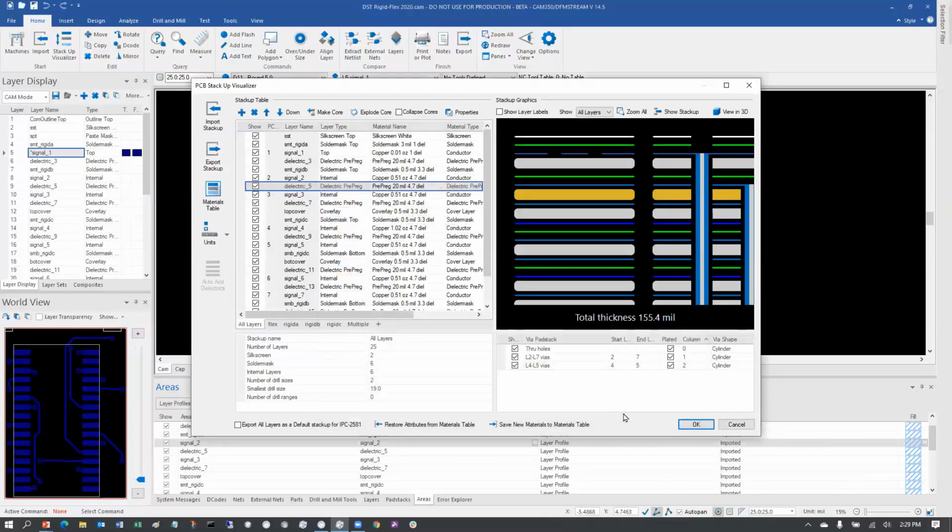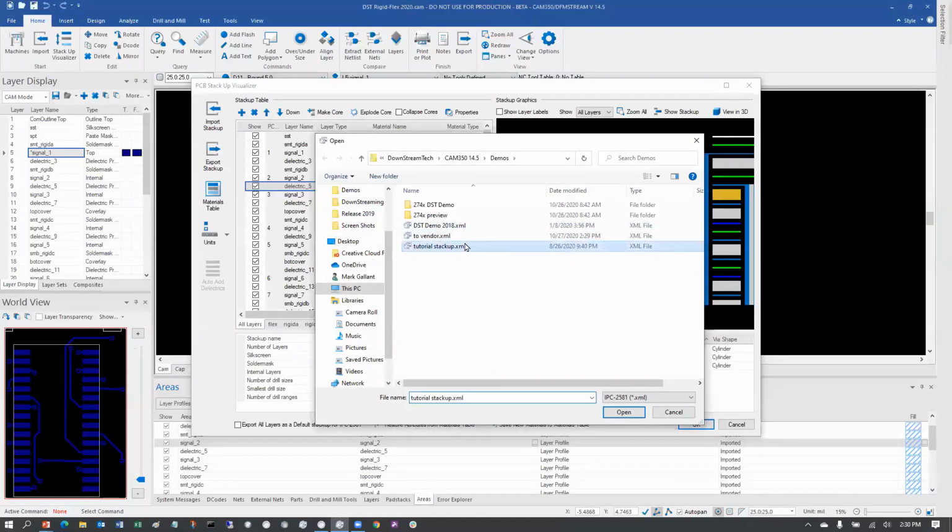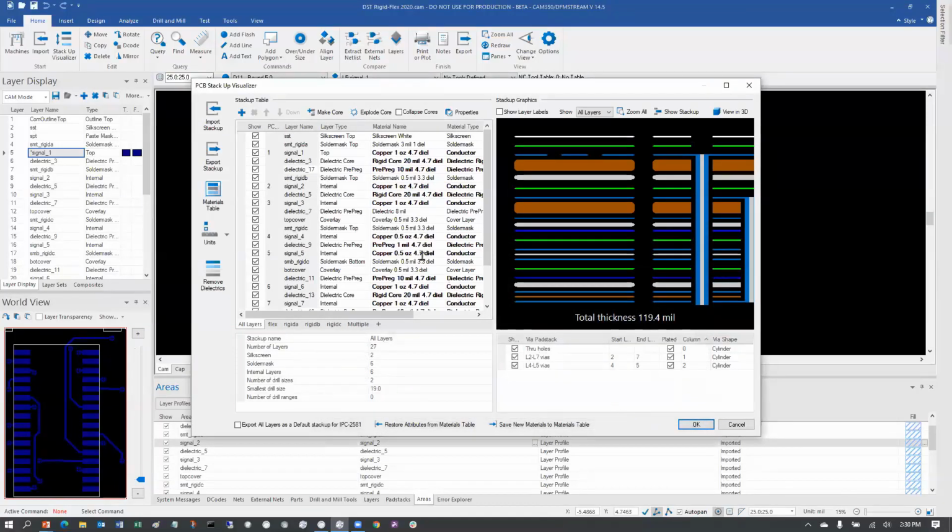It's an HTML file. It's really a 2581 file. He has a tool that he can read the 2581 file in, look at the Stackup layers, say, yeah, I don't think that's right, and he sends me back a revised Stackup. So I'm going to go ahead and import that Stackup. And let's see what happened.